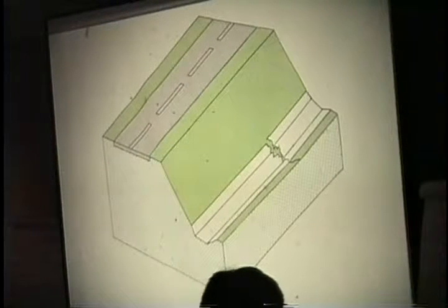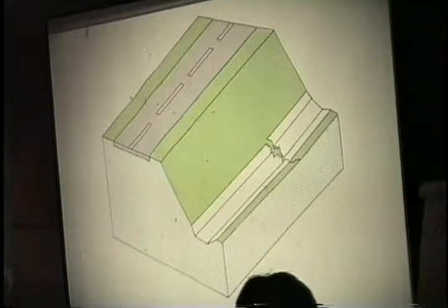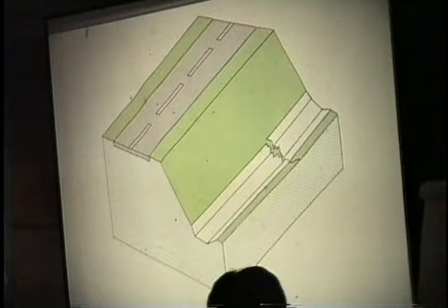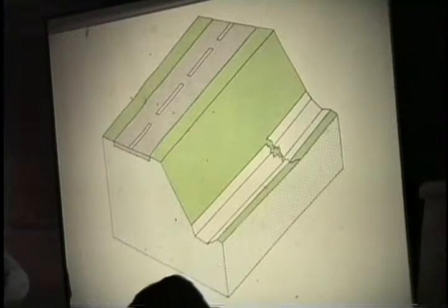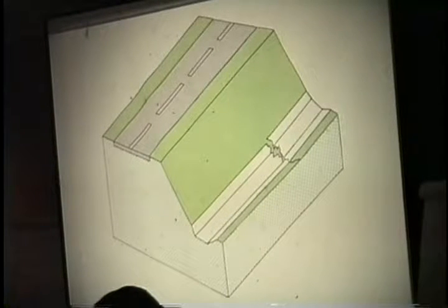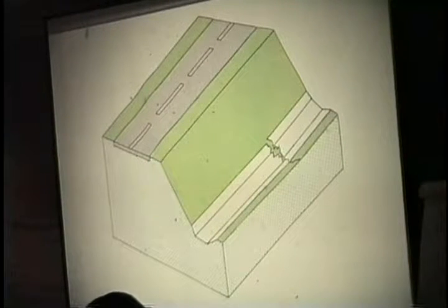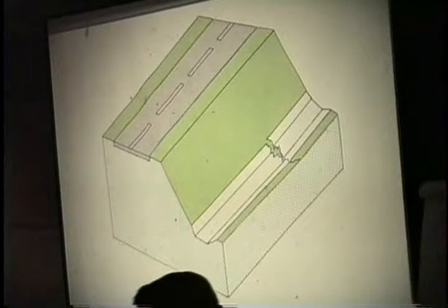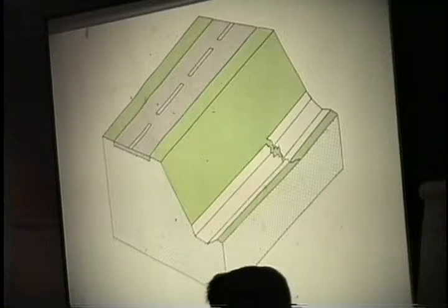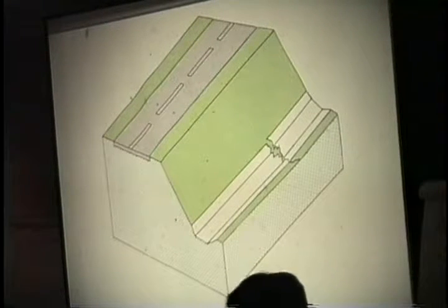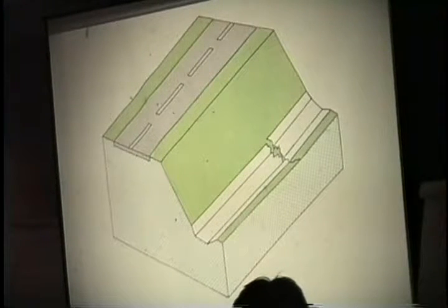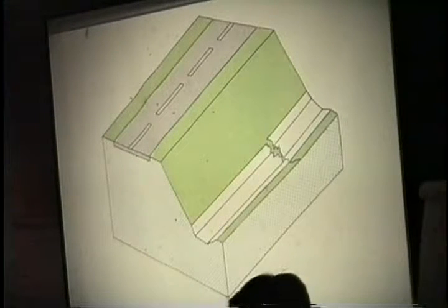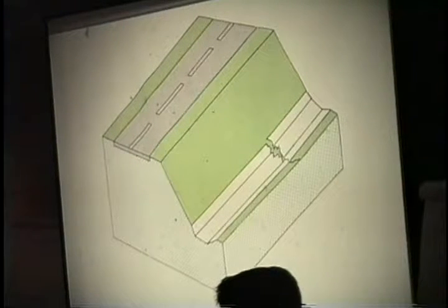So you don't have to do all this high pollutant stuff when you're using it as a maintenance product. But if you see those pipes with the sock around it, don't use that, because that fabric has a good chance of being the wrong material. Those things might clog up, they're very thin. So we'd rather just cut off a piece. You can test to see if it'll clog, and if it doesn't, then use that.